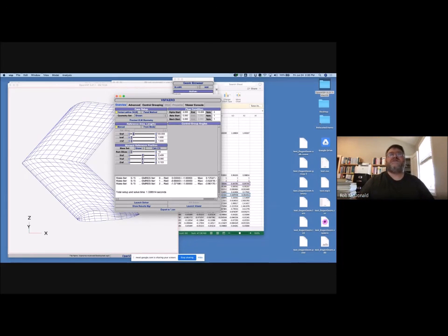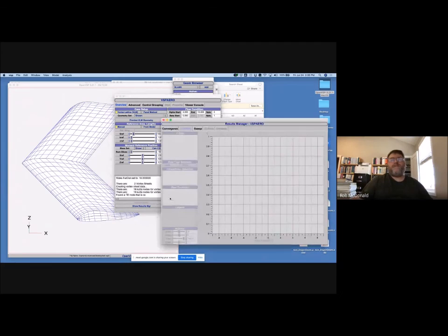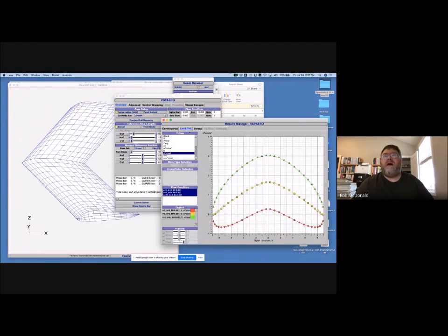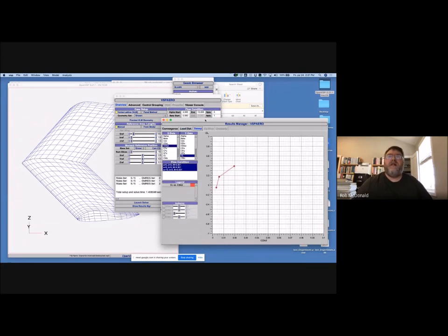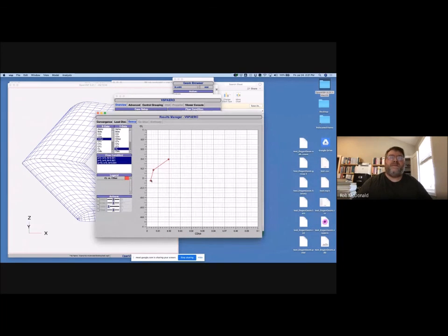But let's reduce that a little. So let's put it at 2. And we're going to run VSP Aero. And I'm going to look over here at the sweep tab. That's where the chart is sweeping the 3 different runs that we had. On the x-axis, I'm going to plot our moment about CMY. Actually, I'm going to flip those. I'm going to do CMY on the y, and CL on the x. And this chart is what you want to look at to talk about stability. This is the main chart about the stability of an airplane.